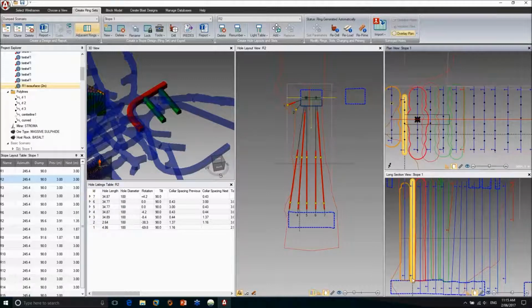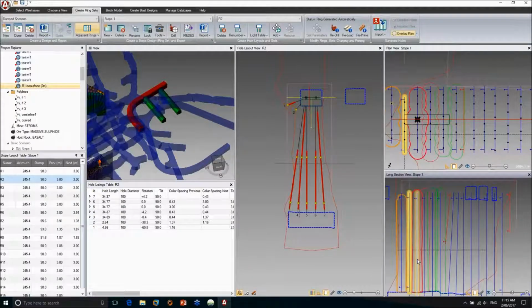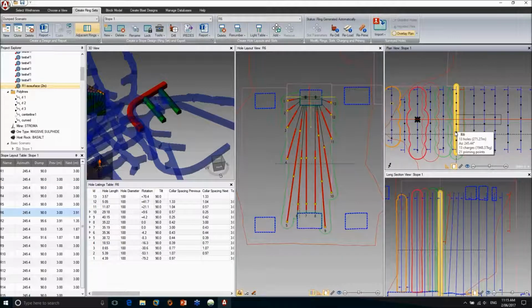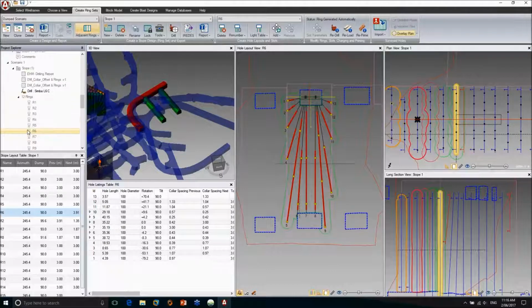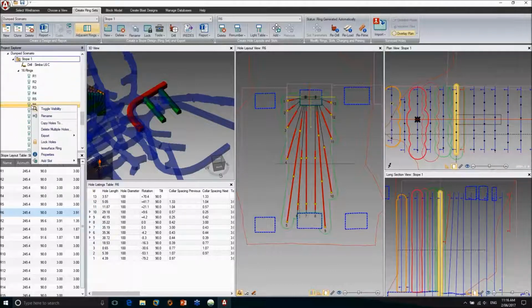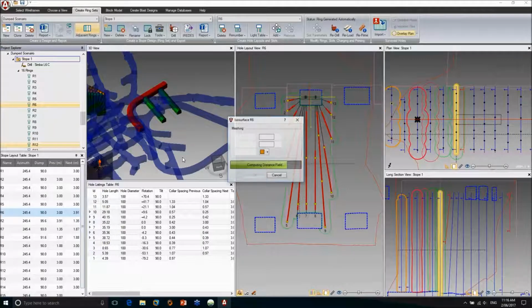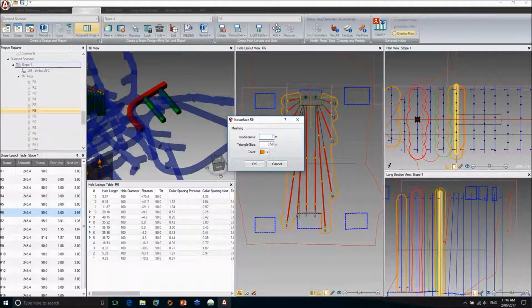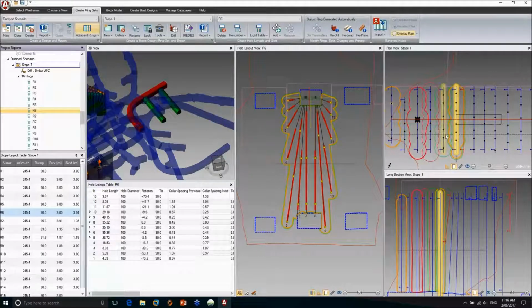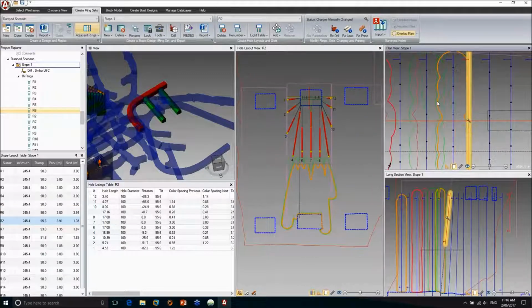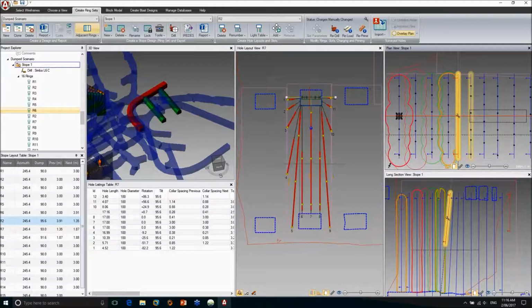So if I were to, say, take the second ring, oh, that's already in a scenario. So I've got another ring created for ring 6. Let's isosurface that ring again. Maybe I want to do like a 1.8 meter offset from the holes. Alright, so I've generated this orange one. You can see that the green one was at 2 meters, the orange one is at 1.8.